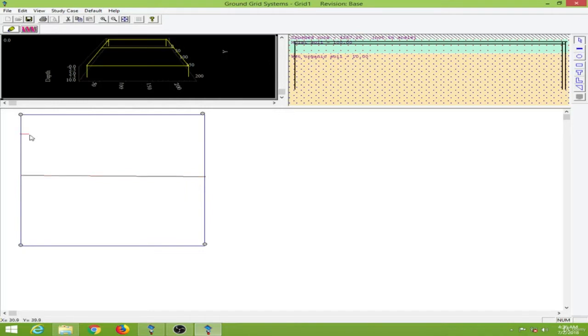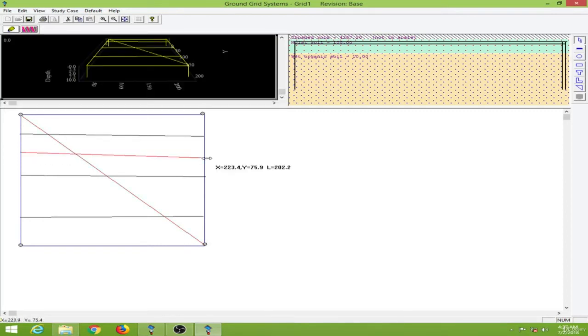So using the finite element method, we can design any shapes we want to, because there is no restriction on the shape as in the IEEE standard, and we can place the conductors with unequal distances as well. I can also place this in several angles. Okay, let's try to simulate this.